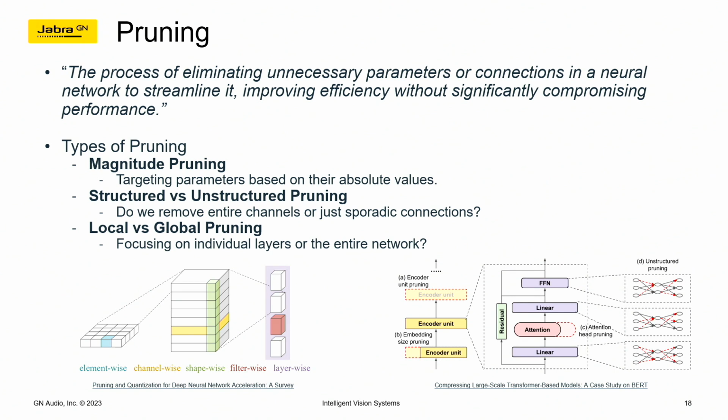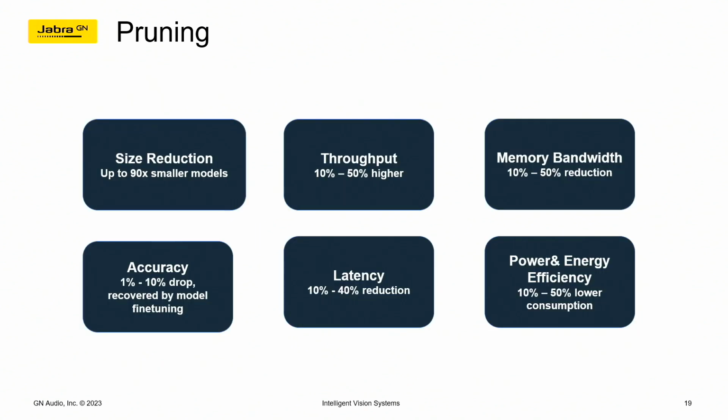Another thing you can do here is optimize the whole multi-head self-attention layer as well. As it is, it takes around order n square multiplication operations for just the MHSA. You can take it down to order linear time complexity easily if you are careful enough with the design of the MHSA block itself. And these are, on average, some numbers that you can get in terms of the key metrics on the hardware.